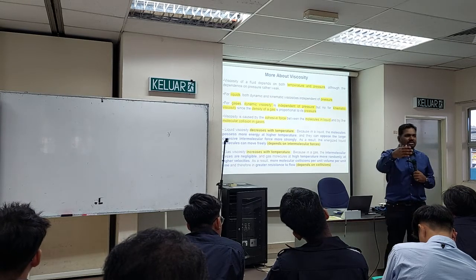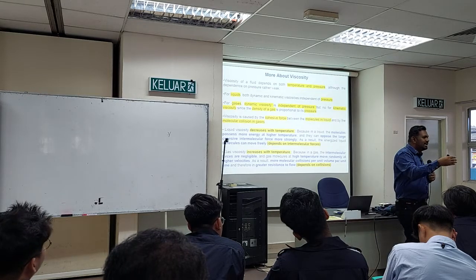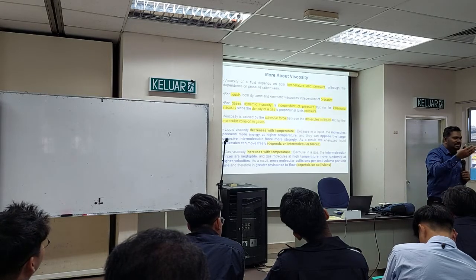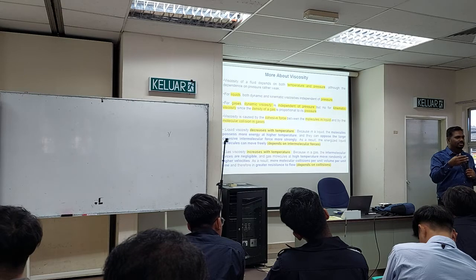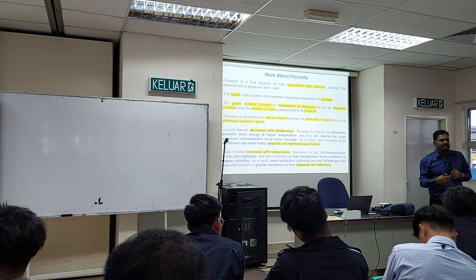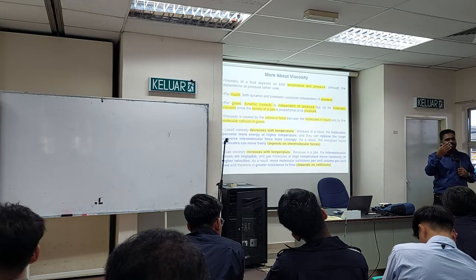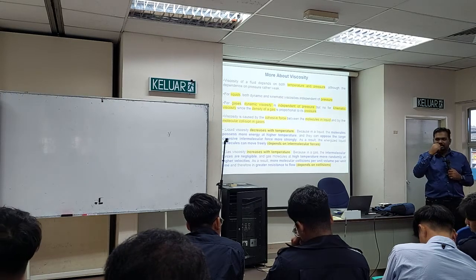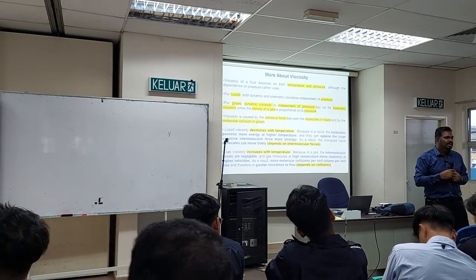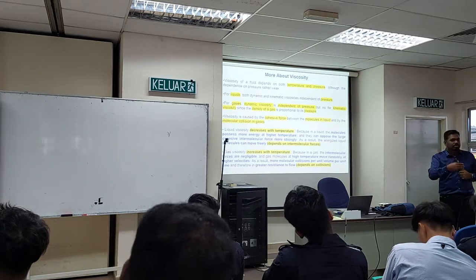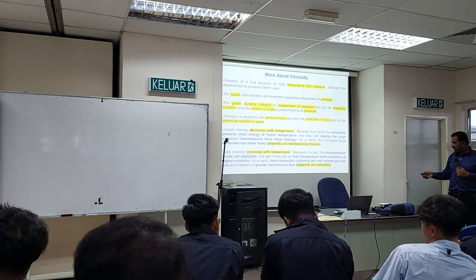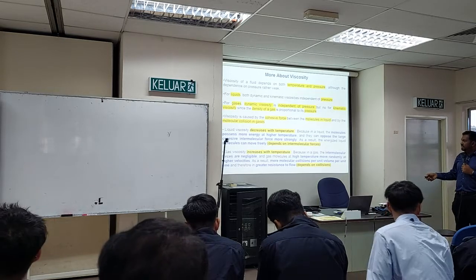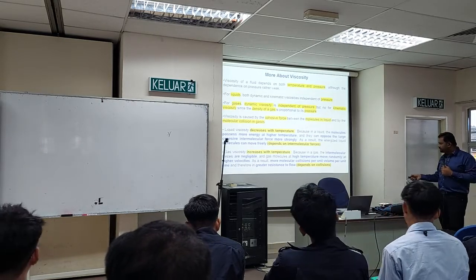Okay, and it depends on the engine oil too. There are many, fully synthetic, semi synthetic. So it depends on your engine oil. But usually 5000, 5000, 7000. Fully synthetic maybe 10,000. Okay. So change it first because liquid viscosity decreases with temperature.